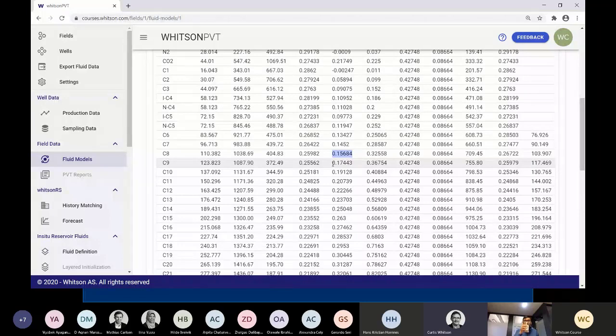So that number, the S number, the dimensionless volume shift factor, is an approximate representation of the error that the uncorrected equation of state would have. So it gives you the magnitude directly. It's not exact, but it's an order of magnitude, and it changes for each component. Just kind of a curiosity. Very good, Curtis.